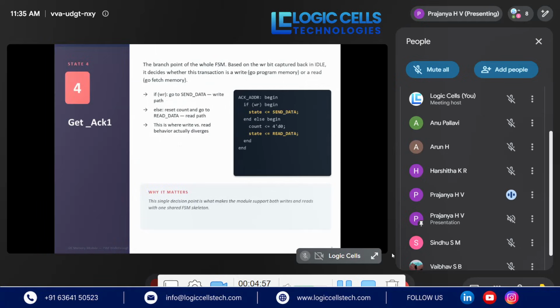Next it moves to the get acknowledgement state, where it receives and checks the acknowledgement after sending the address. This state is important as a decision point. If WR equals 1, it should perform a write operation. If WR equals 0, it has to perform a read operation.